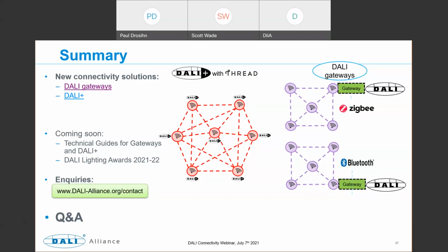So if you had, let's say, 3 DALI LED drivers, in the future the gateway might make those look like 3 separate Bluetooth lighting devices or Zigbee lighting devices, allowing access to the data separately and control separately. But that's not part of the specification yet. That's probably the primary requirement to add next. I think it is probably the most requested requirement.